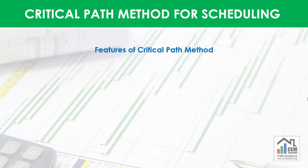Besides this basic framework, there are some features of this technique which differentiate it from other scheduling techniques. For example, CPM uses deterministic approach. This means that it is based on realistic values which are achievable and accurate. In CPM, duration of activities are determined from past data, like productivity values of resources. This makes these estimates accurate and reliable.